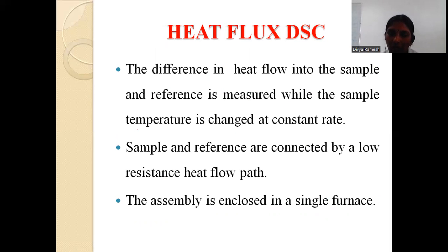When a temperature of 100 degrees Celsius is applied to a specimen, how it reacts can be studied with the help of these power compensated devices. The name indicates power compensated device, DSC. Power compensated in the sense how much energy or power is required to maintain the same temperature in both the sample and specimen can be calculated, and with the help of that parameter you are going to study the temperature, thermal stress, melting point and heating point of a particular material.